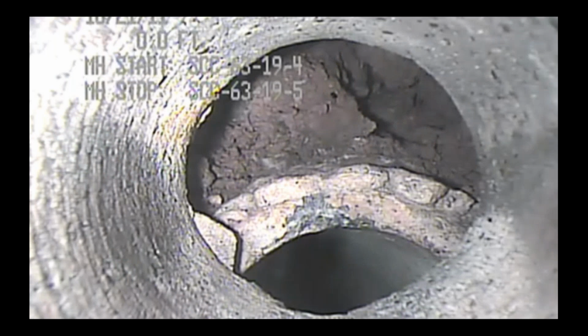Now, this is an extreme case where we have differential settlement at a conduit joint. The location where this is most likely to occur is either at an anti-seep collar or at the connection of the conduit with the riser structure. Most riser structures, the foundation is deeper than it is on the conduit, and the conduit could be placed on compressible material.